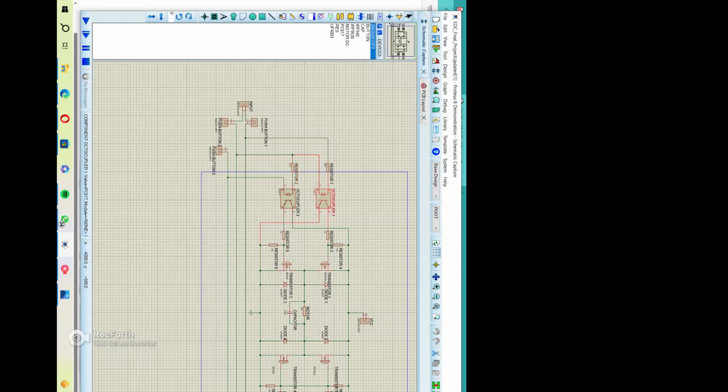This is a resistor of 470 ohm. This is also a resistor of 470 ohm. Each 470 ohm resistor is connected with an optocoupler for isolation purposes. Next, the optocoupler is connected through node 4 to a 1k ohm resistor. The same goes for optocoupler 3. The optocoupler is basically a PC817. So this optocoupler is connected to terminal 3 with resistor 5 of 1k ohm.